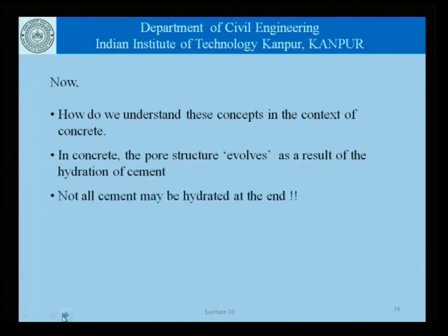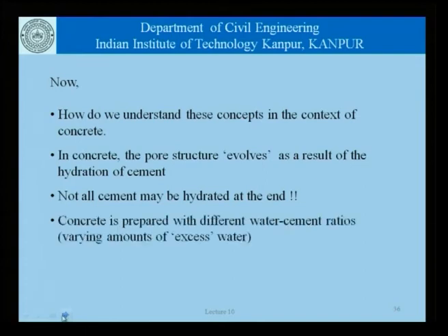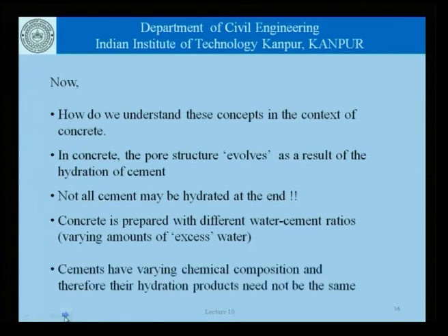Not all cement is hydrated at the end of the day. Concrete is prepared with different water cement ratios, which leads to a varying amount of excess water. Cements have varying chemical compositions and therefore, their hydration products need not be the same.